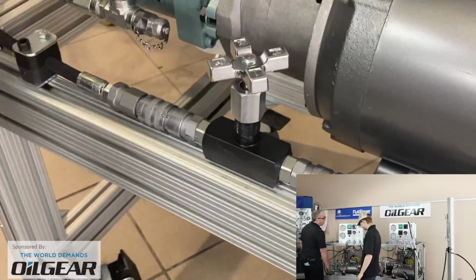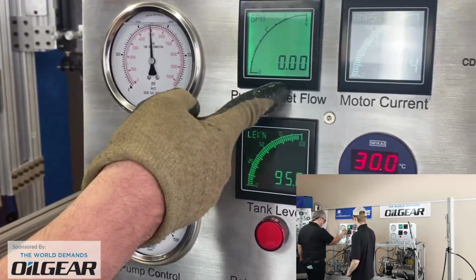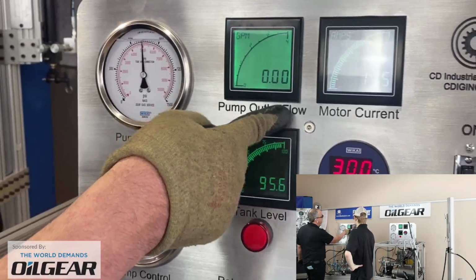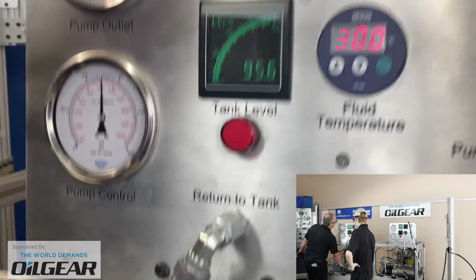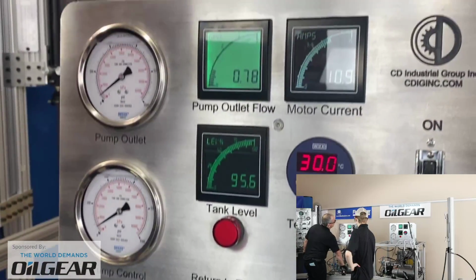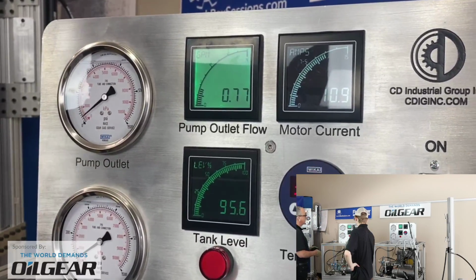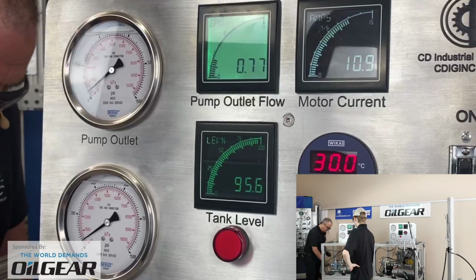Okay, but if we want to change the maximum flow, we were at 0.7 or something when we were wide open. This is obviously not the time to change maximum flow rate, the maximum volume stop on the pump, because we're currently in the zero flow condition. We need to open the system back up for free and easy flow. Perhaps 0.78 gallons per minute is not correct. Perhaps what we were supposed to be set to is 1 gallon a minute.